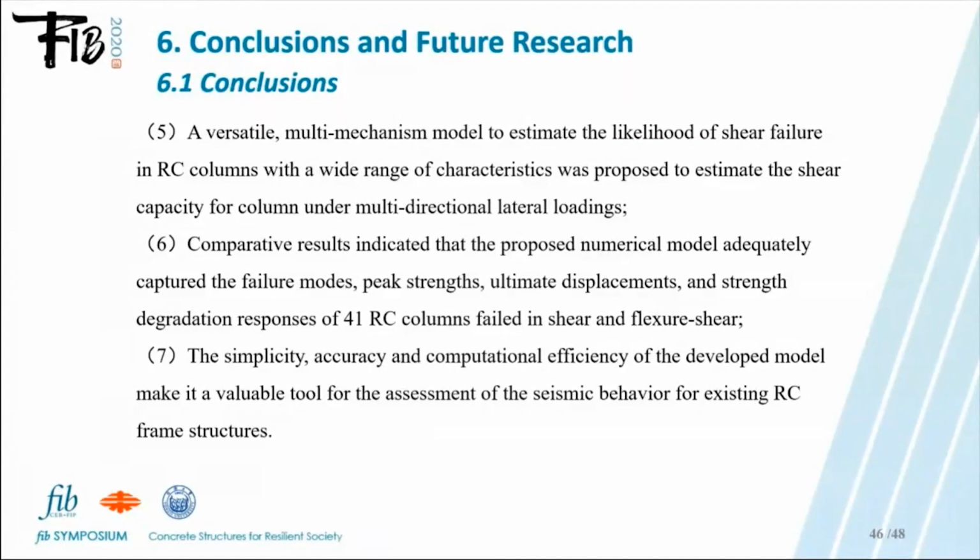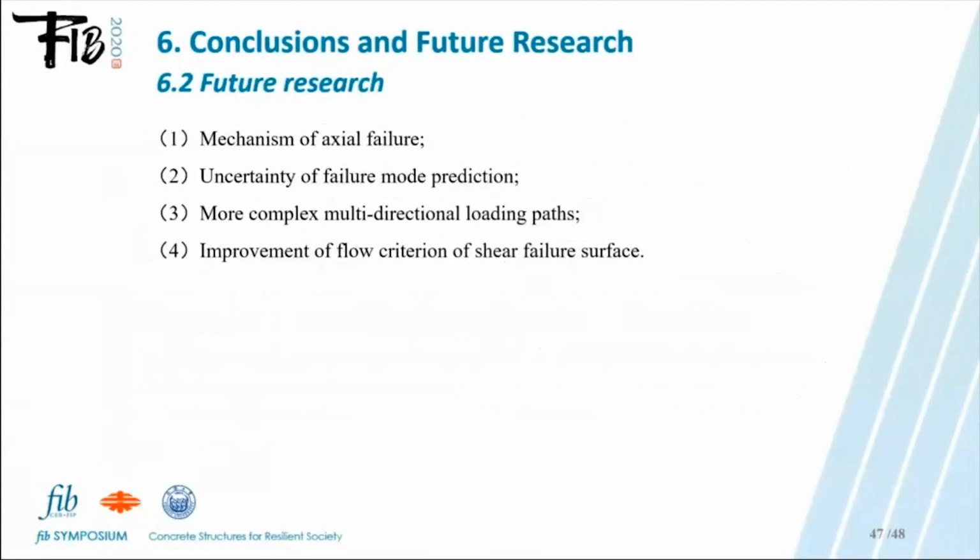Comparative results indicated that the proposed numerical model adequately captured the failure modes, peak strengths, ultimate displacement, and strength degradation responses of 41 RC columns failed in shear and flexure-shear. The simplicity, accuracy, and computational efficiency of the developed model make it a valuable tool for the assessment of the seismic behavior of existing RC frame structures.